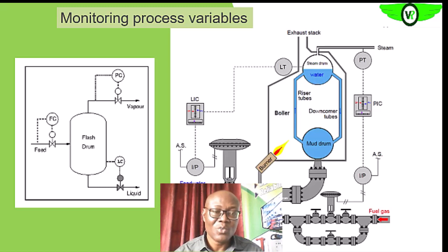They will go into the vapor state, and those vapors will rise up, while those that did not flash out, those that are still liquid, will remain in liquid form and settle at the base of this drum. So it is a kind of separation process where you separate the lighter component of the mixture from the heavier component of the mixture.